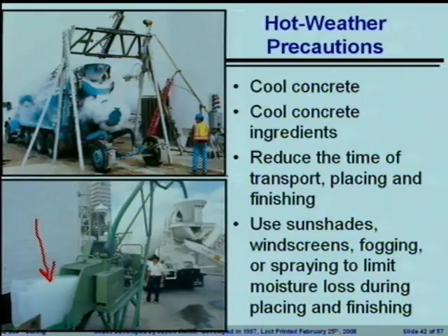And there's going to be limitations on how hot the concrete can get before you start to place it. And depending upon where you are, those limitations are actually going to change. Can you cool it down enough to affect the rate of reaction? Yeah, they will be cooling it down quite a bit. Here you can be dropping the temperature 15, 20 degrees Celsius. And you're doing it before it gets back into the back of the drum.